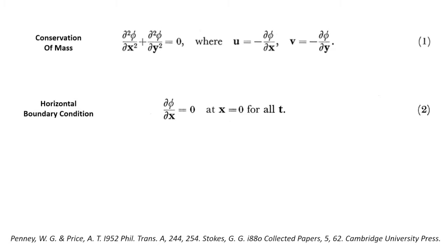We can then apply the boundary conditions of the tank. So in the horizontal dimension, the x component of the velocity must be 0 at the breakwater, which in our system would represent a wall of the tank. And by the same token, the vertical velocity component must be 0 at the base of the tank.